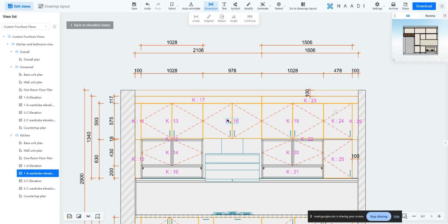Okay, this is called deduplication. If that is removed, you will see two dimensions repeated at the same extent. That will be an unwanted dimension, the duplicated dimension. So in the backend, we follow something known as the deduplication process, where the tool will understand the model alignment. Based on the model alignment, it will decide which repetitive element dimensions there are, based on alignment similarity, and it will avoid them. So yes, that is the output you're seeing here because of deduplication.